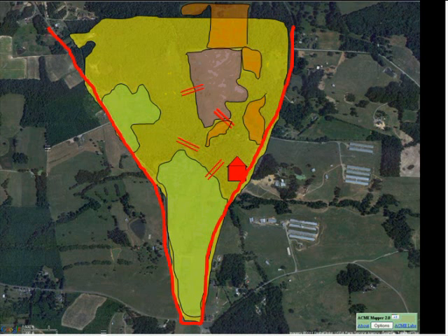They presently use 4 stream crossings to access all parts of the property from the farm headquarters and spend some time on each one every year performing maintenance to keep the crossings clear and operational. Since the farm is bounded by county roads on all sides, at least 3 of these crossings could be removed if the landowner is willing to make changes to present operations by using existing roads to move cattle and equipment to different parcels.